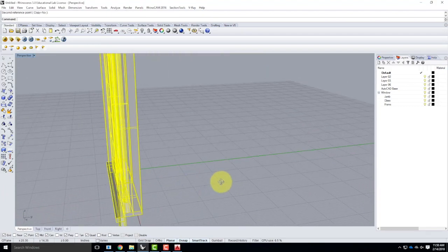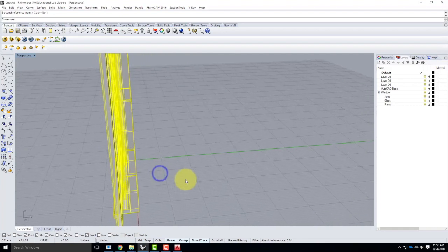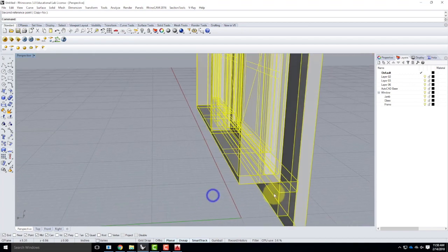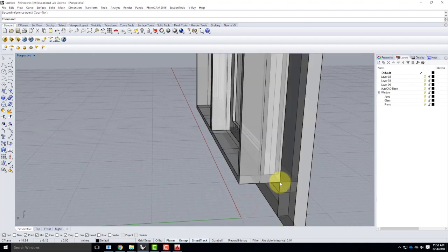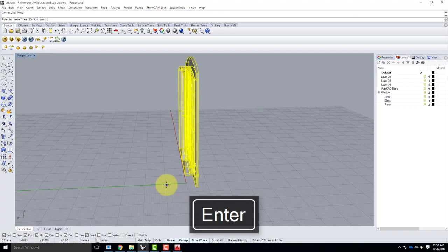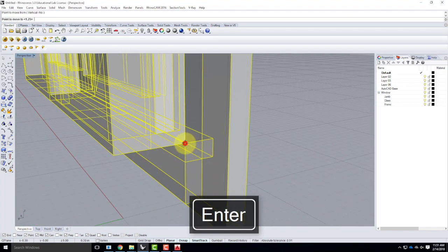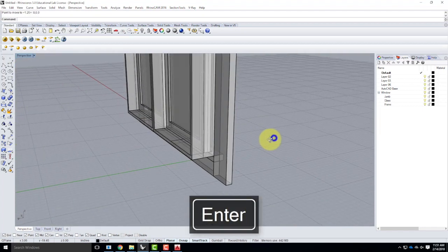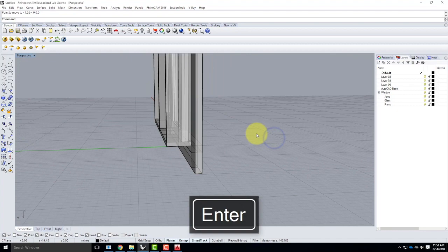It would help, though, as I started to create this, if you think about putting this window into a hole that was in a wall, where I'm inserting and snapping to makes a difference. So this point right there, right here, is probably the hole in the window on the outside. So let me take that point and move it to 0.00 for when I bring it in later. So let me take this, move 0, 0, 0. And now when I insert that as in a block, I can pick just the outside corner, outside lower corner of